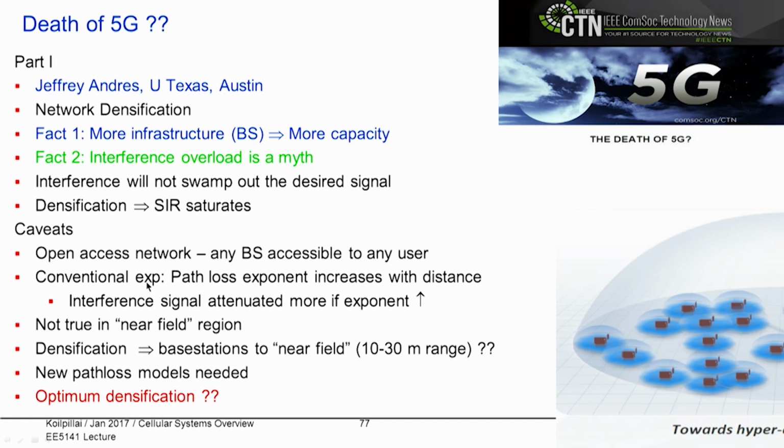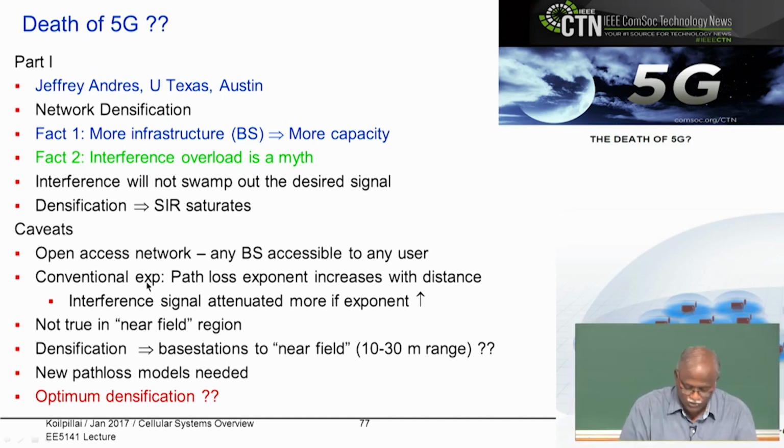Okay, that's the assumption. Now, let's say you have set up your own femto cell, and your neighbor says, hey, can I connect through your femto, and you say no. Then what option does your neighbor have? He has to connect to the macro network. So you may have created a zone in which you have reduced the interference. But if the others cannot connect to the nearest base station, then they are actually going to create more interference, because you are causing interference to your neighbor. The neighbor has to transmit with more power to reach the network. So there is an implicit assumption that we need to look at.